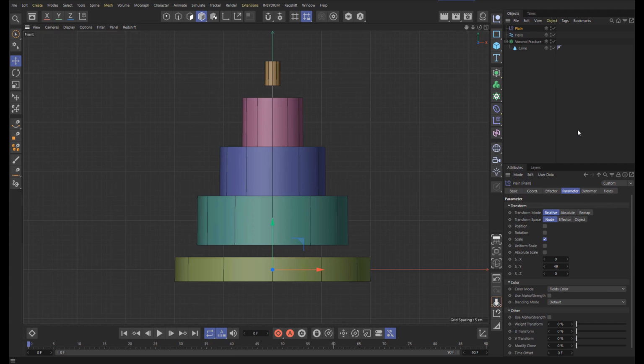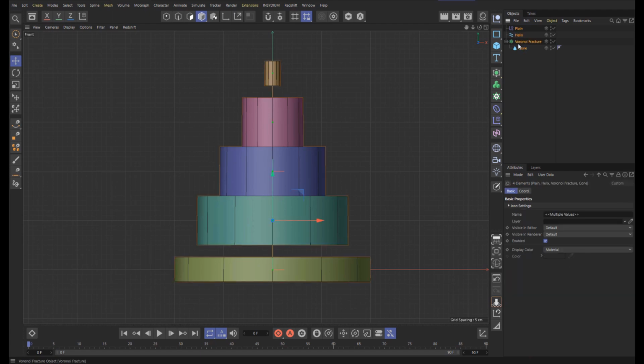So before we get too far, let's start building a rig now that we know some of this math and how it works. So do a little bit of organizing here. Since eventually we want to create some kind of an object we can save as a resource, I'm going to select all of these objects and then type Alt G to group them.